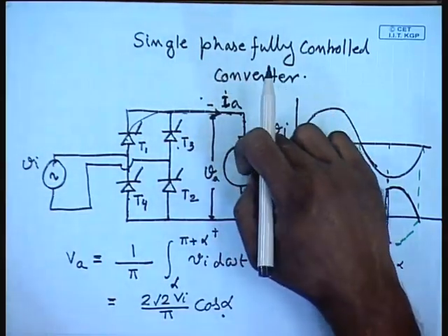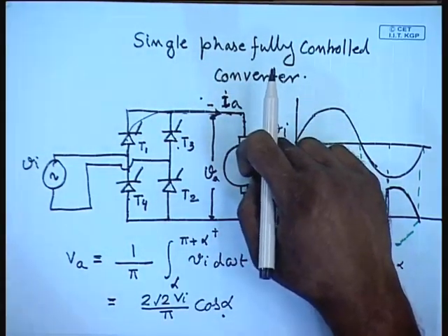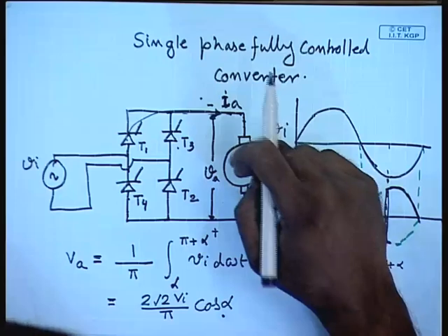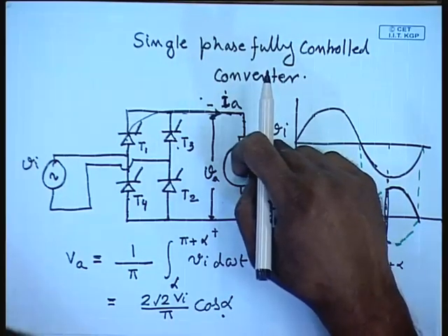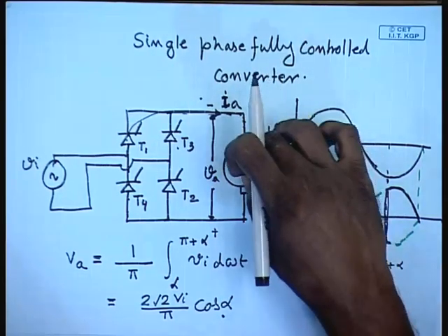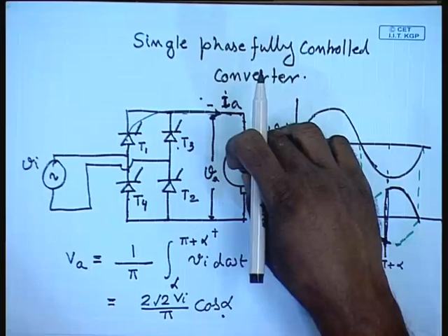Hence, regenerative braking is possible, but for that the direction of rotation of the motor must reverse, that is the back EMF must reverse.